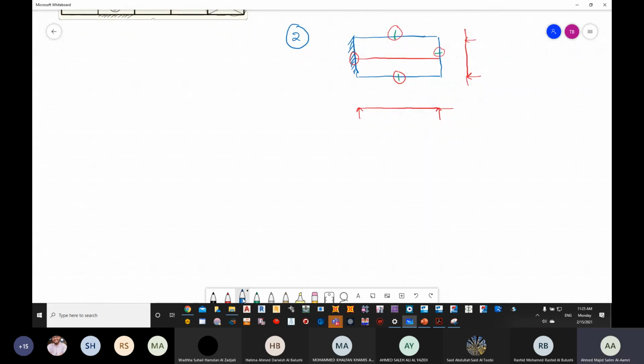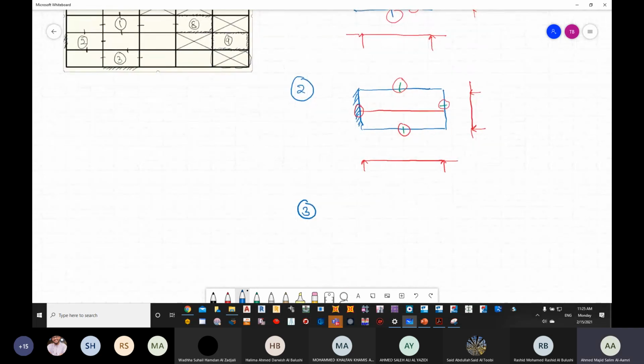Case number 3. Now you see case number 3, what do we have? We have this type of slab, and then there is discontinuous here. If we want to try to draw, so I'm going to draw here, continuity, continuity, and then continuity. Okay, if I want to draw the slab bending moment, so here it's discontinuous, so no need for extension. Here it's continuous, so there will be an extension. Another line here, so there is a slab, so extension. There is another slab, so extension.